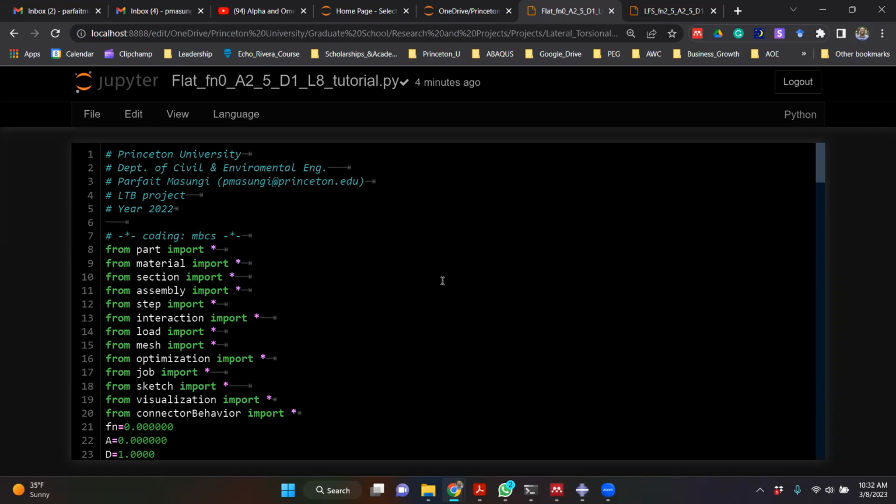You basically have to record a macro inside ABAQUS, and as you're doing the explicit modeling, it's automatically generating the Python script that's needed, and then you can transport that Python script into a much more explicit file that you can start to edit to automate your modeling process. There's a tutorial video that Dean Adab had made, and you can check back in that video to look at the basics on how to do it.